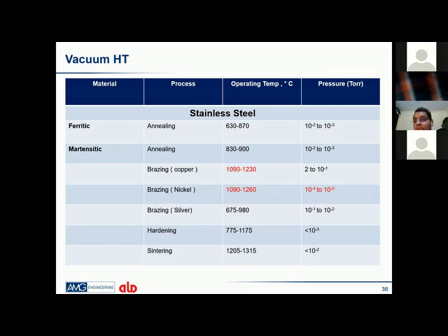So most of the time CFC fixtures are used. Then there are different non-metallic things which are also being developed. There is a new development where CFC fixtures with ceramic have been used at this high level. Similarly, for the -4 and -5 vacuum level, the cleanliness of the part and the inside of the furnace is also really important for getting a very good quality of the part.